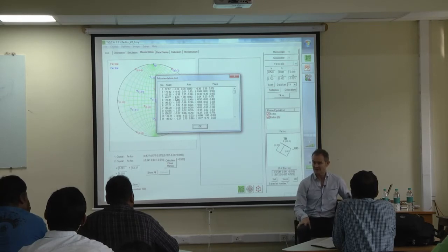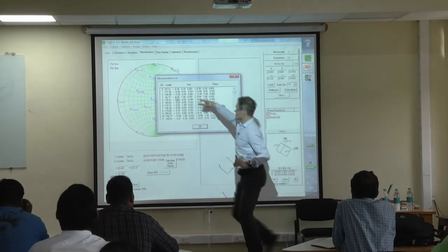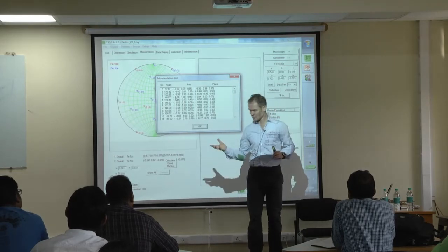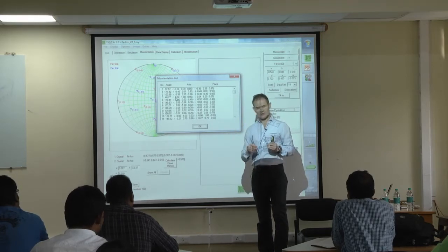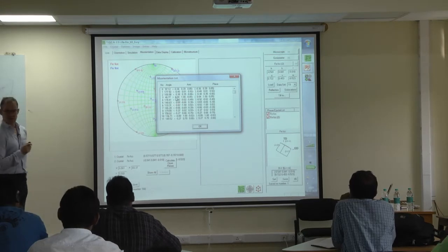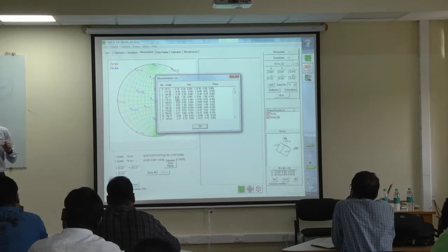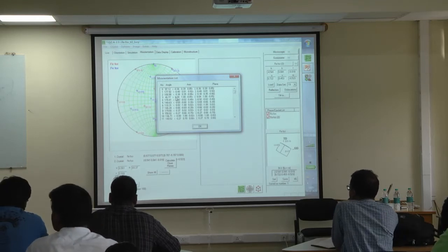Which do we take? When I want to report that in a paper, or when I want to write this is a large angle grain boundary, is it 100 degree? Is it 177 degree? Is it 46 degree? 133 degree? What is it, this boundary? And actually, one has created a definition, and that's purely only a definition. There is no physical reason to select that. It's just in order to make life easy for us. One has decided to take that one which has the smallest rotation angle of all this list, and whose axis is in the standard orientation triangle. You remember the standard orientation triangle of cubic was this funny little triangle where all possible axes appear once, and this is the definition for misorientation.